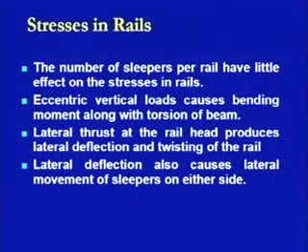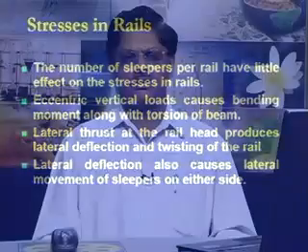Now, the lateral deflection may also be caused due to the lateral movement of sleepers on either side. This is another case where the sleepers which have been provided at the bottom have not been placed in such a way that they remain in place whatever other types of loads come up. If there is any movement of the sleepers, then because of that movement, the lateral deflection may get caused.